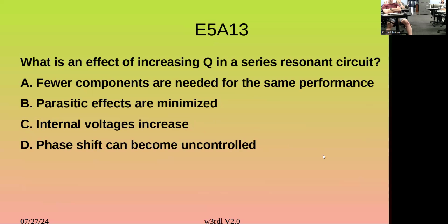Even if we're looking at doing an end-fed half-wave antenna build, and most of the designs use a little 100 picofarad capacitor on that, and even doing it on a QRP radio, it still needs to be a very high voltage capacitor, because you can get some very high voltages on the end of that antenna.